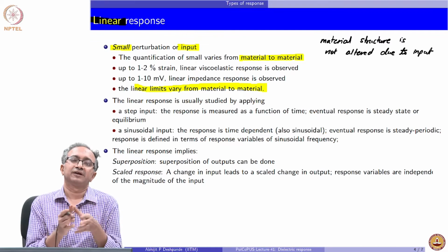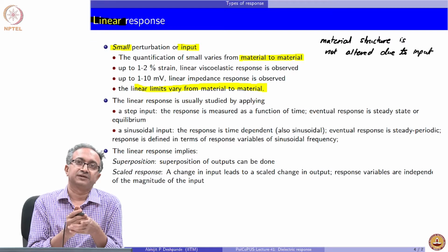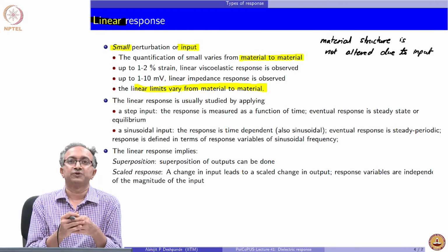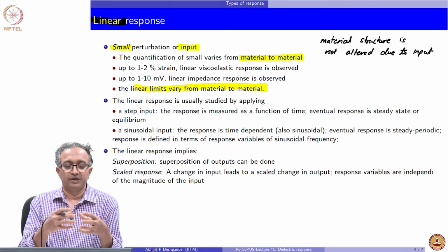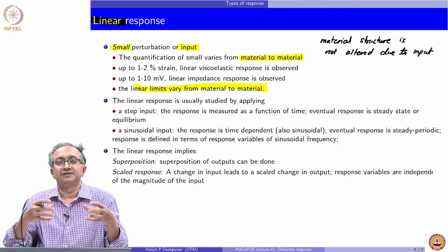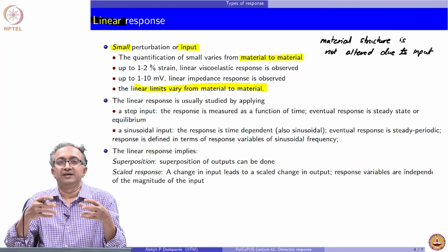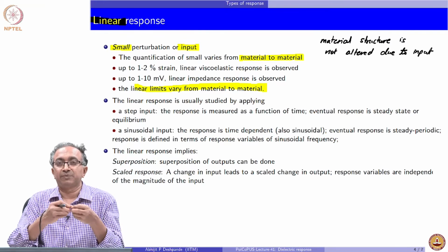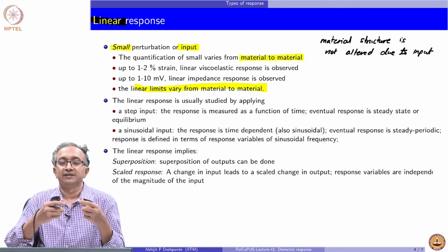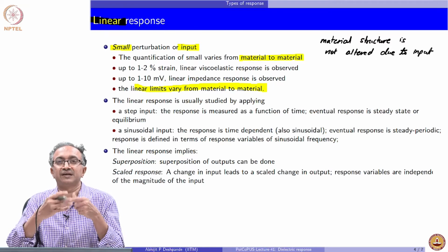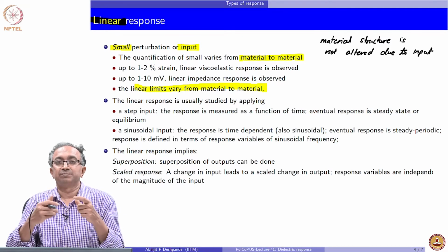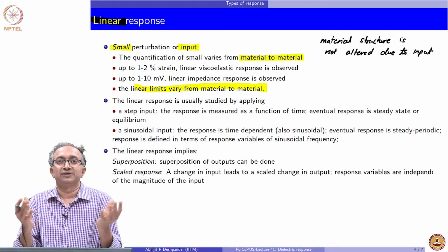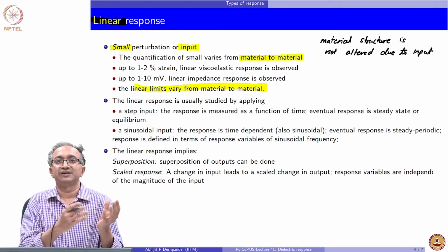For example, if we are looking at, let us say, a thermoplastic sample which is being deformed, if we apply a small amount of strain, then the molecules basically just get displaced with respect to each other and then they can come back. So, this is a small deformation. But if I apply a strain which is a little larger, then some of the entanglement points slip, the polymer chain gets oriented, and when I now release the load, it will not go back to the earlier state.